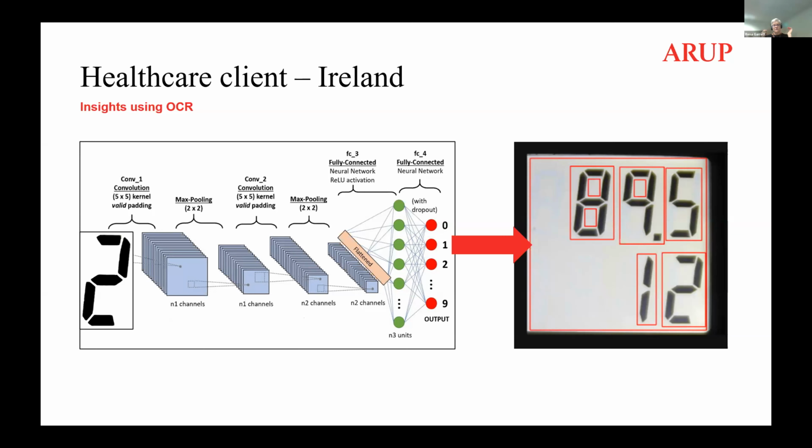to us, where we put it through a convolutional neural network with a number of different layers that we had trained to see different digital values. They all varied from place to place; they weren't always identical. And then we did optical character recognition on those digits and were able to interpret the reading from the meter. And we fed that into an analytics engine and trended that over time, and we're able to display that then in the web front end to the client.